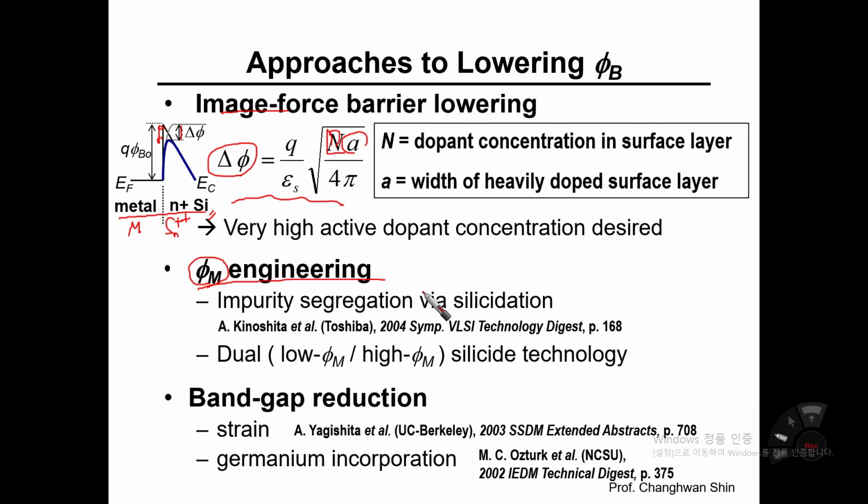However, if we can do some magic to tune the silicon at the atomic level, for example by stress engineering, or by doping the silicon with atoms such as germanium, then the silicon material's original bandgap energy could be tuned.